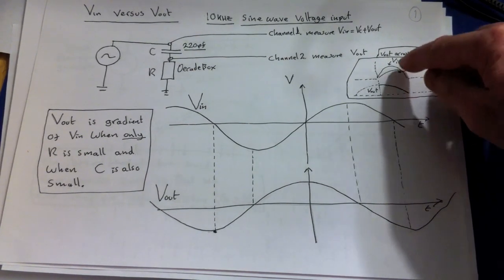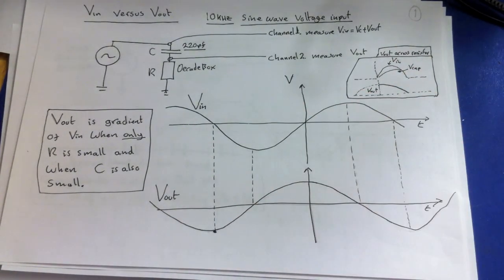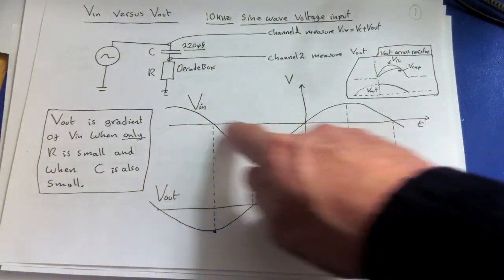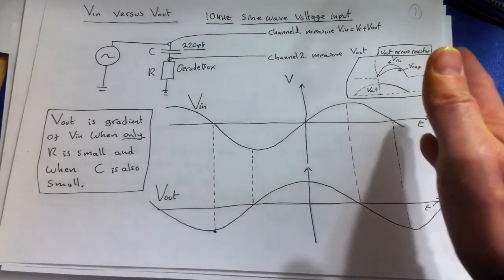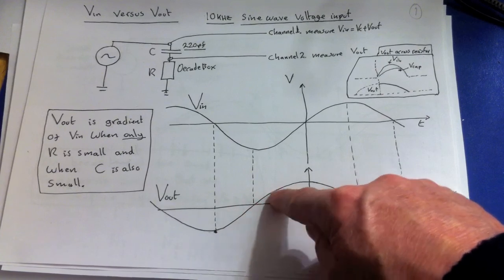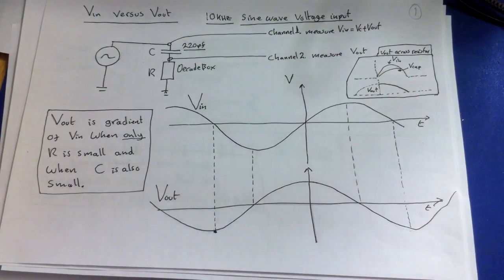And then of course as it's a sine wave, it'll come back through here and we'll go on. We'll be able to see all that. As we discussed in the tutorial, the pattern that we make here is like a 90-degree shift, or a pi/2 shift, so that this voltage out, which again is the proxy of the current, is leading the voltage in by pi/2. So let's have a quick look at that now.